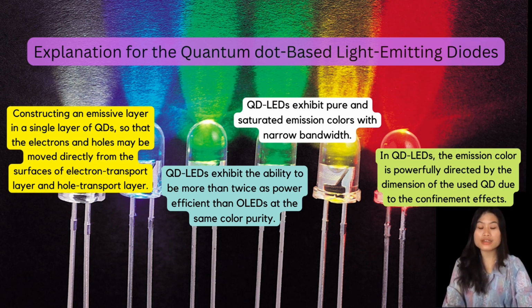The color rendering index, CRI, indicates how accurate a given light source is at rendering color when compared to a reference light source. The higher the CRI, the better the color rendering ability. Light sources with a CRI of 85 to 90 are considered good at color rendering.